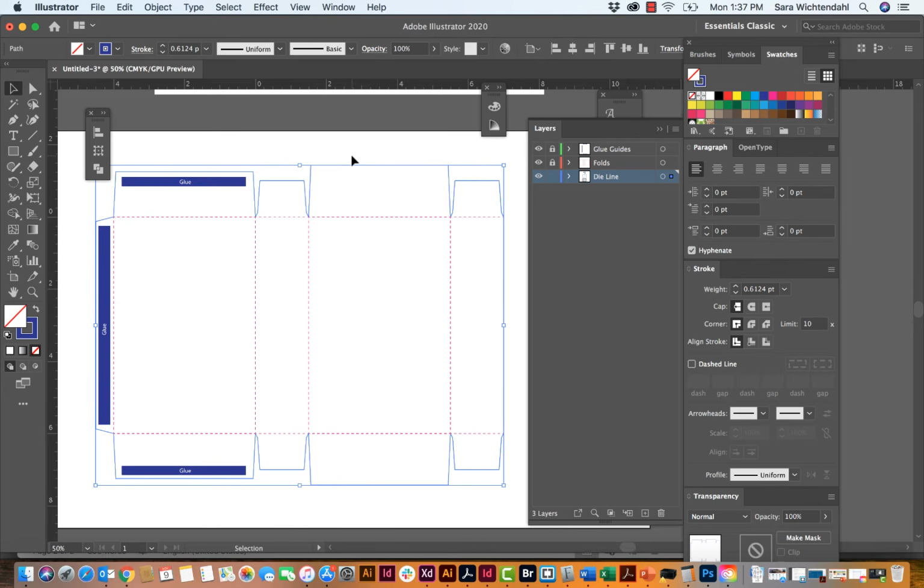You may need to check specifics with your printer if you're doing a flexo type of print, sometimes large pieces of packaging with plastic or something like that, they may need a larger area, but typically industry standard is 1/8 of an inch of a bleed beyond your die line.